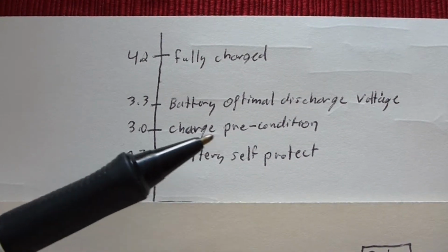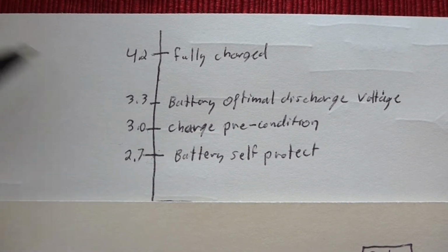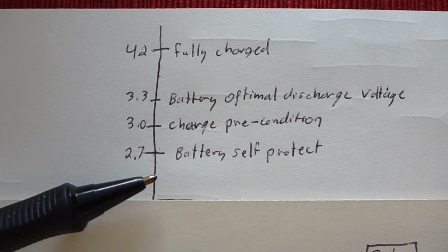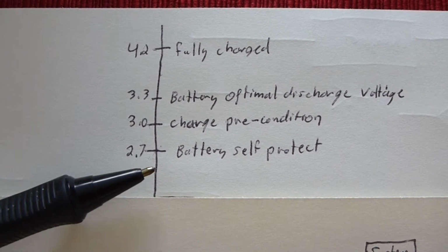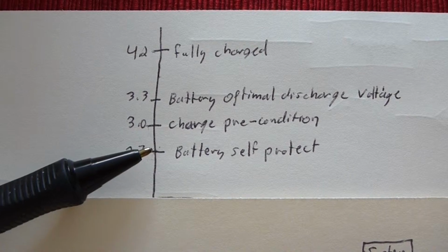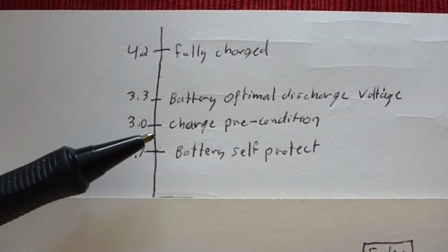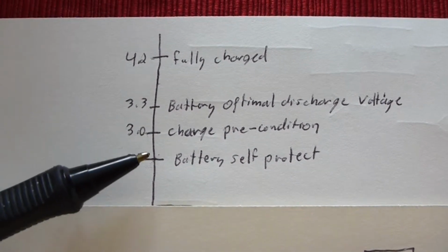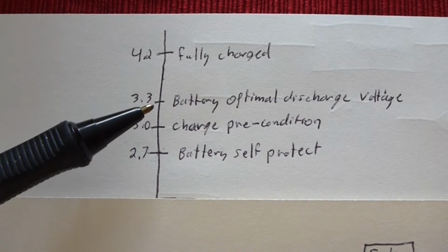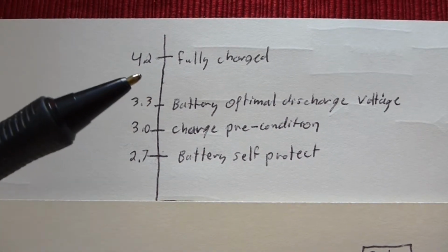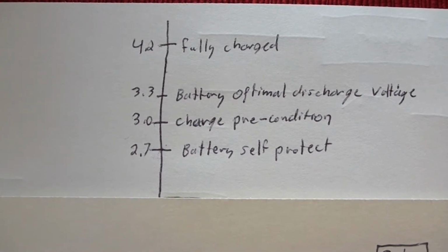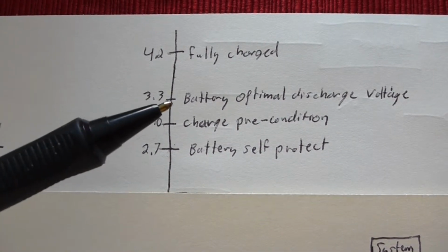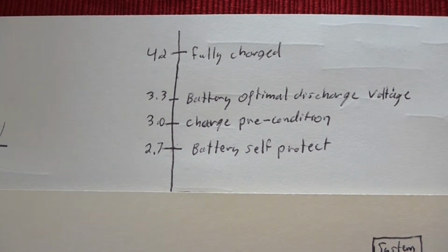The preconditioned charge mode's only difference is that it only charges at about 10% of its normal rate. So effectively, it will prevent it from exploding, but it will also charge very slowly through this range. And we don't want to wait for that, so we'd rather just not go into this range. We have the solar panels to recharge everything. We might as well just say, you know what, shut off here just to be safe, charge back up, and then come back on a little later. So that being said, it's very important to shut off the battery at this 3.3 volt level.